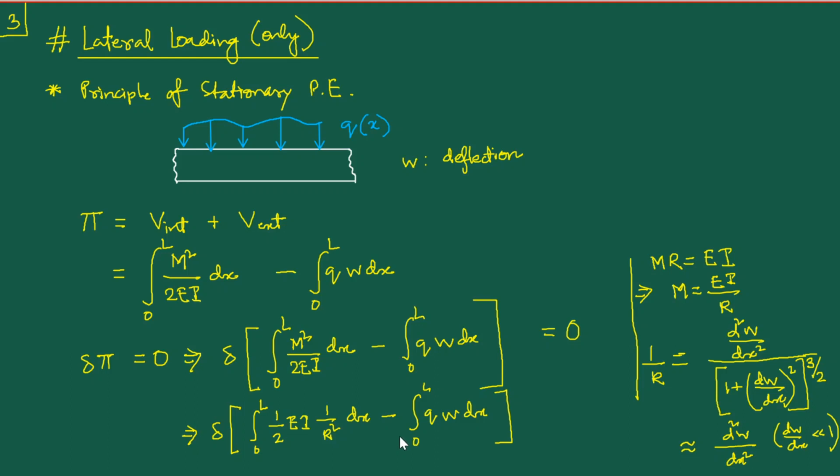Okay, so inherent in all of these derivations is the Euler-Bernoulli beam hypothesis. Let me write down here. So we are very much working under the assumptions of the Euler-Bernoulli beam hypothesis, which we all study in our undergraduate mechanics of solids, as well as we are using this linear elastic material behavior.